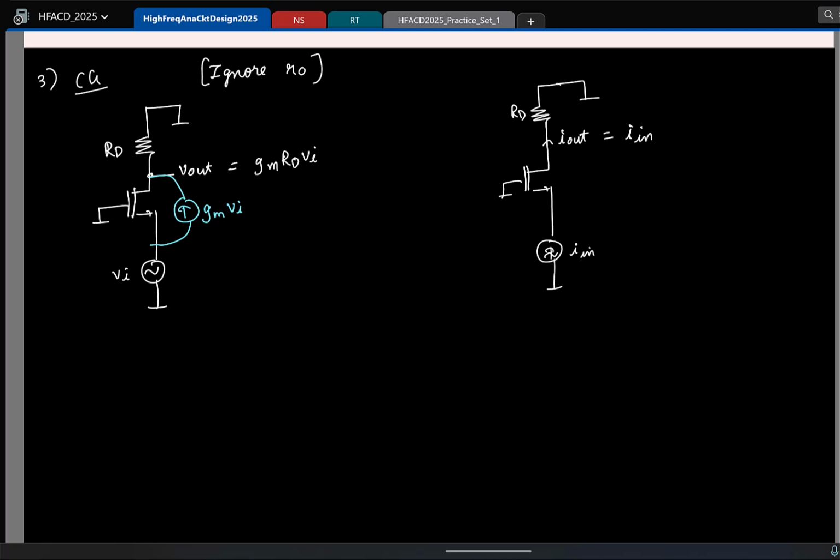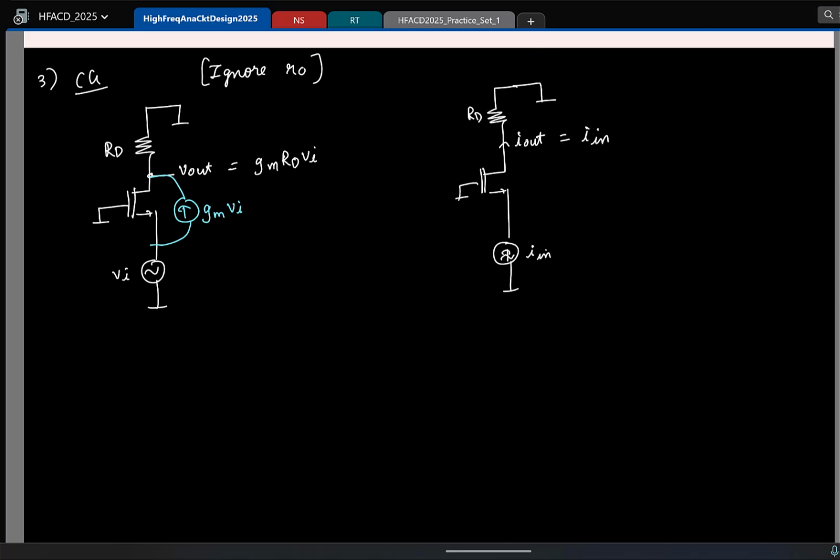Now with respect to currents, I see that the gain is 1. So what is the point of the circuit? It's a current buffer. What kind of controlled source is a current buffer? Current controlled. It is sensing some current and buffering it as a current source. It's a current controlled current source.